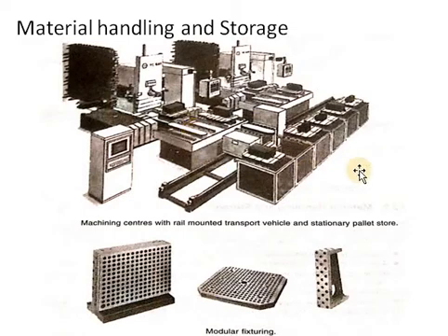If you're talking about compatibility with computer control, the handling system is controlled directly by the computer to direct to workstations. Load and unload workstations, etc. You can say the material handling equipment consists of load or unload stations, palletizing, and another is robotics, that is AGV, automatic guided vehicles. We'll also see what automatic guided vehicles are, and AS/RS, you can say this automatic storage or retrieval system.